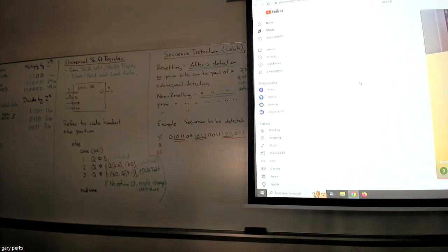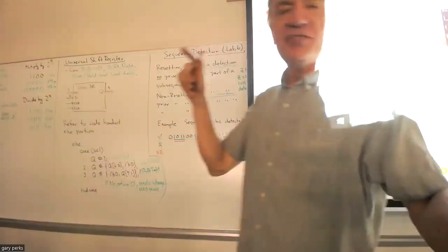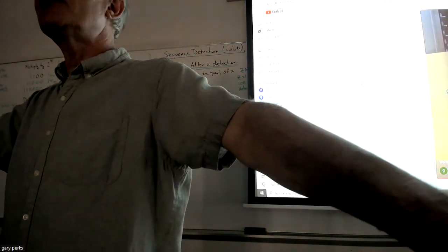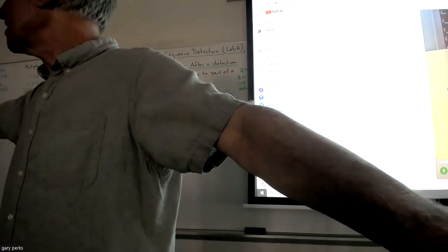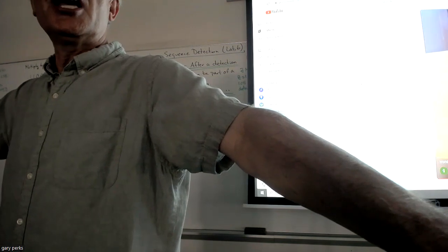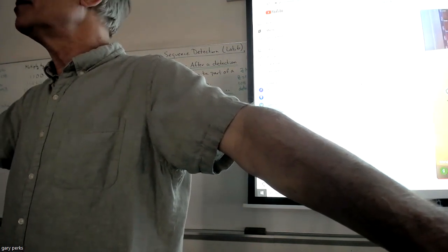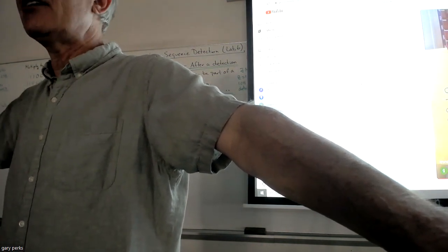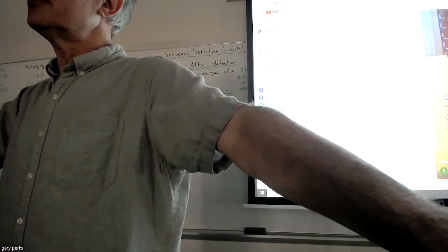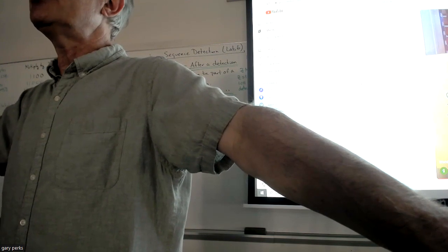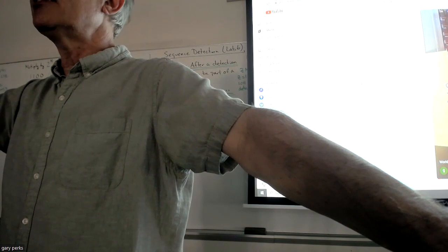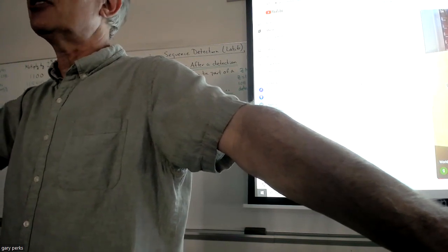The reason for that is because I went into that clock divider module and I changed an integer. Remember we talked about last class that in our example, there was a max count integer. By changing that integer, you change how much that fast clock is being cut down. Even though Dr. Mealy's clock divider module is written in VHDL, it's the same idea. There's an integer that you just have to go into that code and change.